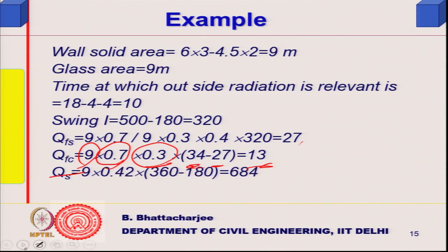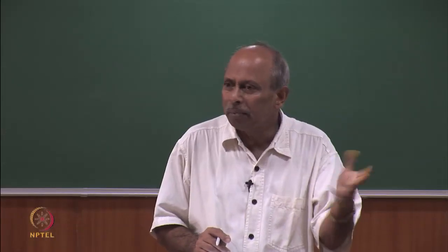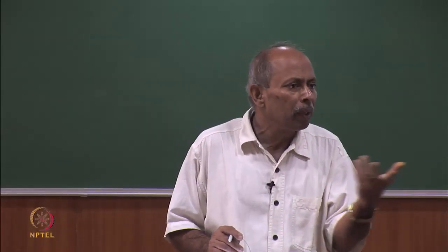Then follow it up with Q direct solar radiation. For direct solar radiation, there is no time lag. So, at 6 pm this is, 6 minus 4, I mean 2 pm, this is 360, because admittance 4 hours I will have to take into account, but I do not have to take into account the glass direct radiation, because it will have negligible time lag.